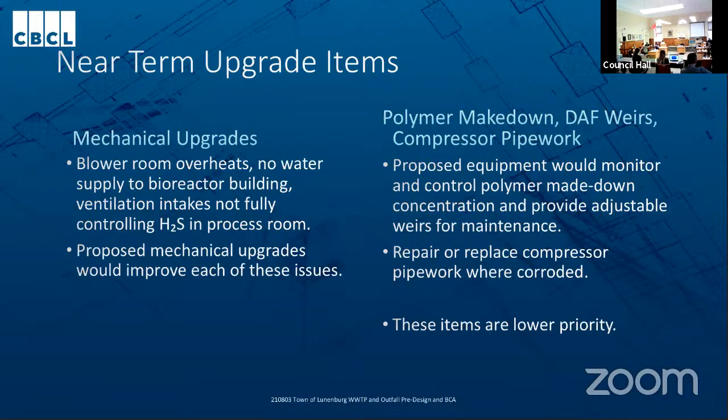It is proposed to remedy this by insulating the air header to reduce the heat rejection from the overhead piping, as well as reinstall an exhaust fan to provide proper heat relief within the room.